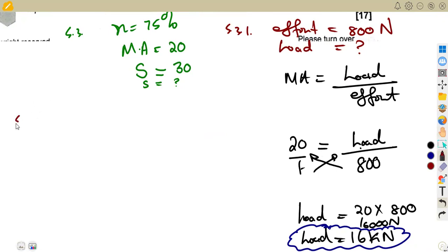So instead, I'm just going to write VR, but that's the displacement ratio, the same as the velocity ratio, which is given as 2S, the number of slots on the larger pulley, over the difference of the number of slots, S minus s. But we do not have this one. So this formula is limited. Remember, we do not have s, right? So let's leave this one.